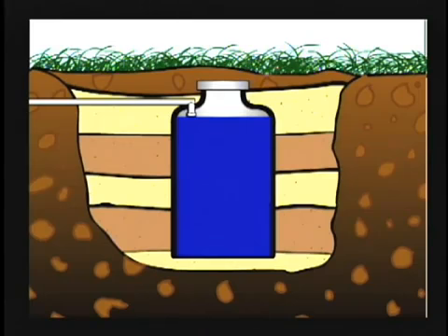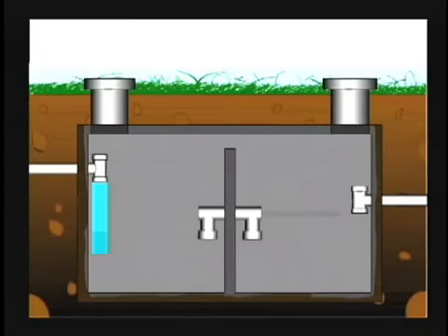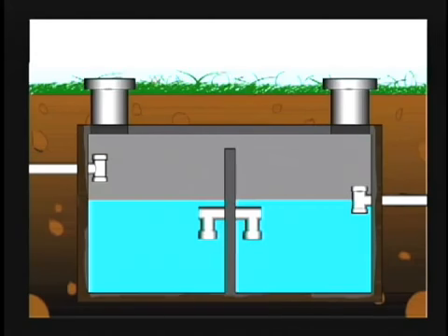Again, backfill the soil 6 inches over the top of the tank. Whether your septic tank is plastic or concrete, fill it with clean water before you put it into use. The full tank allows the baffle between the first and second compartment to keep the soils in the first compartment and away from the drain field.